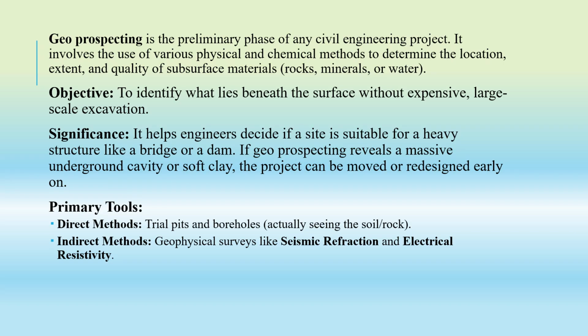So in case I have a soft clay, or it has some underground cavity, or it has a horizontal strata, or sometimes it has a strike or a fault in it, then it will be vulnerable to earthquakes. So we have to decide by using geoprospecting; raw data should be collected before building a massive underground structure or massive surface structures.